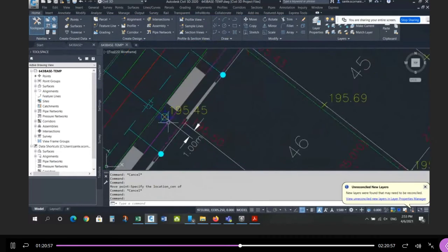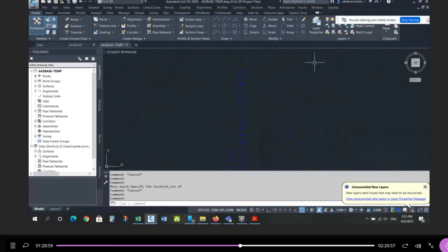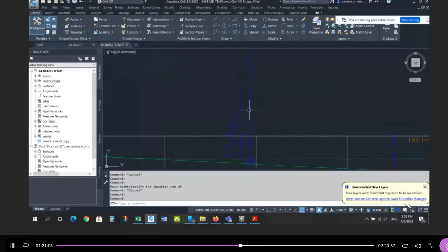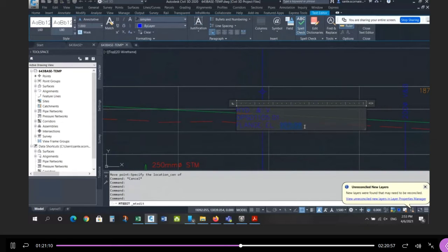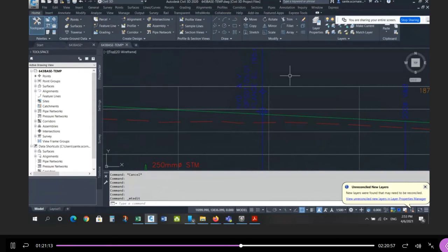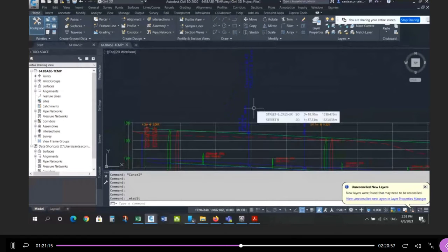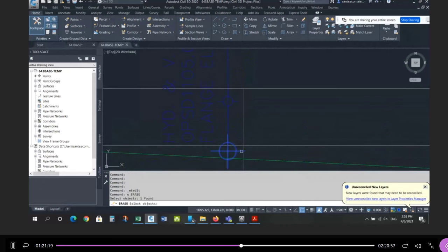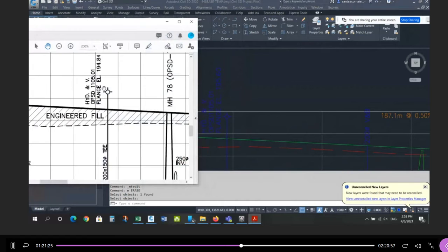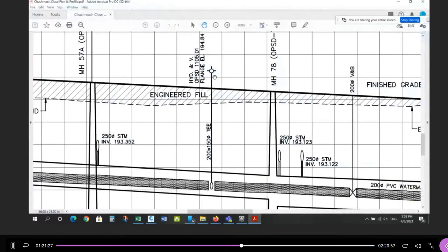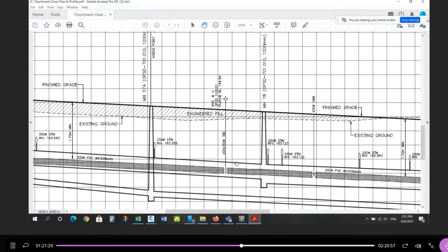And that should be the projected elevation, 545. If we look at the label that I created, 545. I have to add 6 inches, so it's going to be 195.60. That's the flange elevation. So whatever the boulevard elevation is at the bottom of the hydrant on the ground, add 6 inches. And that's how you get the flange elevation on your hydrants. And that looks a lot like this. Okay, so that's how you get the elevation.